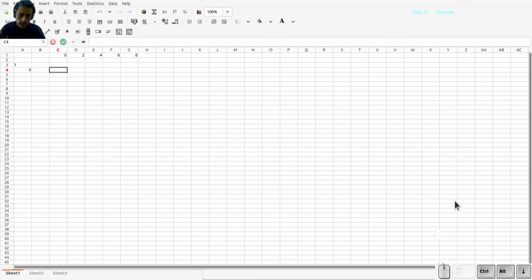Okay, so that's the value that I will put here at all depths at time 0. Immediately after, I have pore pressures equal to 10 kPa. Now I have to look at the time in the past, right? For time, at the first time step, I want to know what my time increment will be. And now I have to go back to this term here.